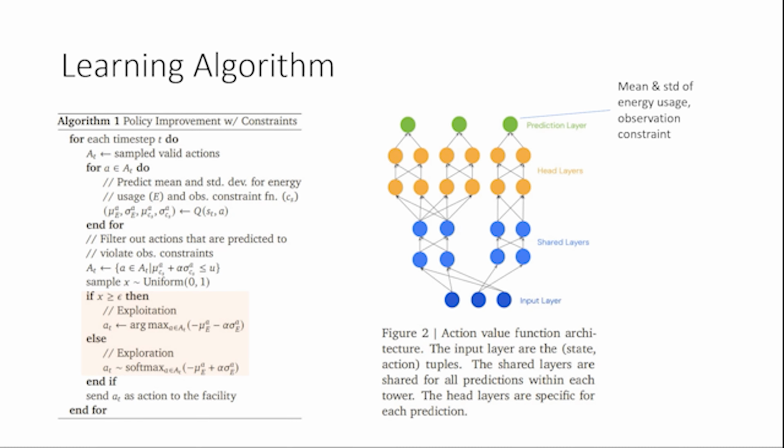Transition function is determined by chiller plant behavior and physical environment. It is responsible for determining the best action to take. The selected actions are filtered by the building management system to ensure that only safe instructions are executed. So how is this transition function learned? It is the same as supervised learning for training a neural network.